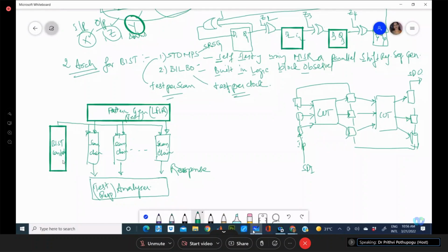What is a normal operation? A shift register operation. While you put it into normal operation, with respect to the system clock, you will be getting the output generated for one clock for each bit, or each scan element.